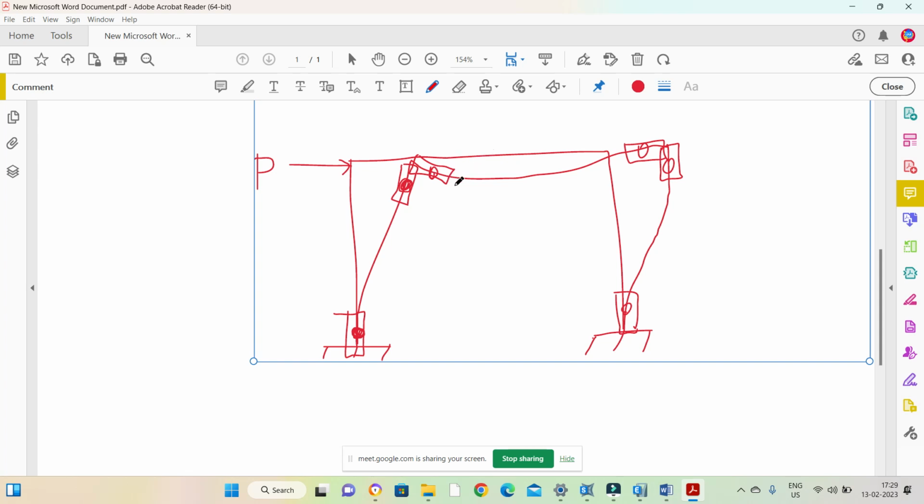It means we are assuming that the failure point is concentrated at a particular point, not in the whole member length. Similarly there is one continuum plasticity, or fiber plasticity, I forgot the terms actually. Concentrated plasticity is the one where we define the failure point at a particular point, as you have seen here. So this is called lump plasticity or concentrated plasticity. Lump, or concentrated. Concentrated you know already. So lump or concentrated.